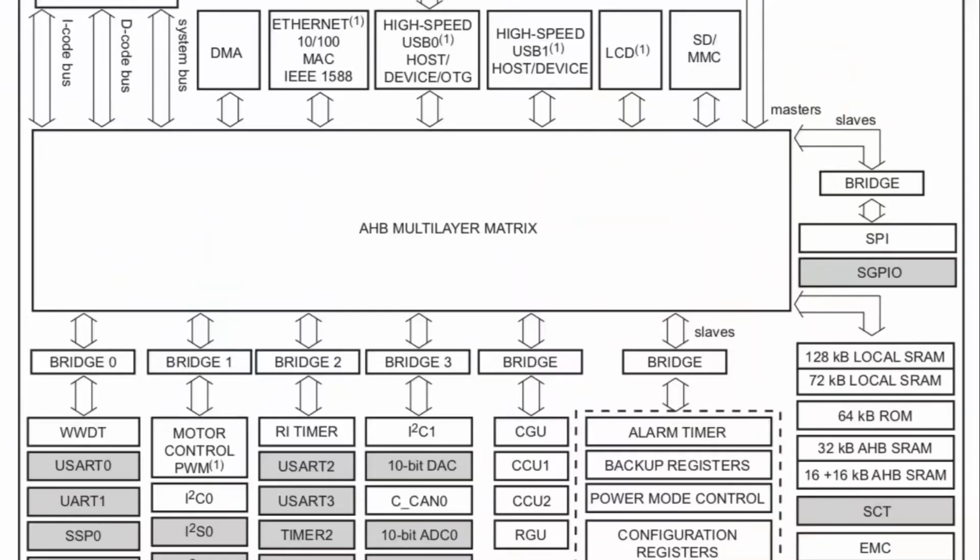So if you look at a typical microcontroller datasheet, what you see is something along these lines. All the little boxes around the outside are peripherals that implement various protocols and things like that. We've got UARTs, we've got USB somewhere on here, we've got ADCs and DACs. This SGPIO thing up here is a high data rate thing. All these protocols that you might want to speak.